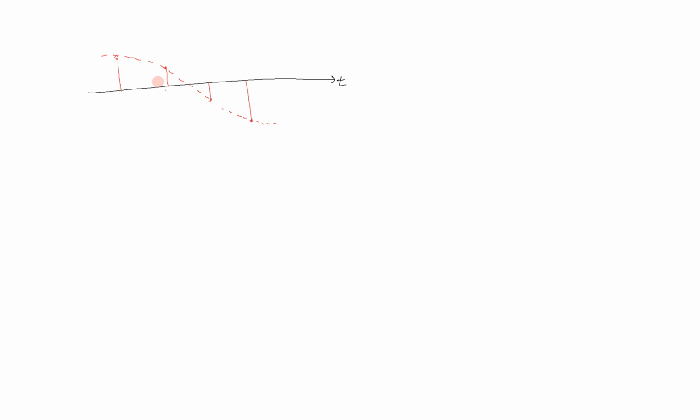For example, let's redraw the same sample pattern. We can place a box or a steady level at each one of the samples until the next one. So something like this. We place a box around this sample at its amplitude. We place another box at the amplitude of this one until halfway to the next sample.